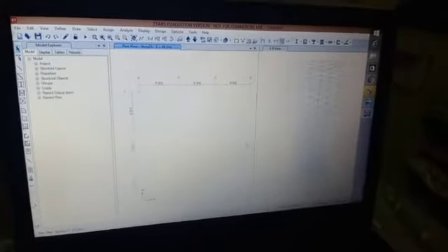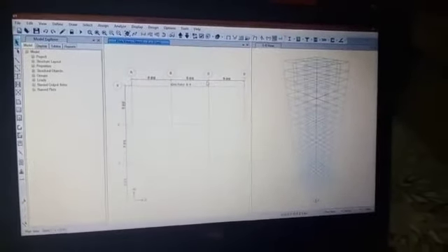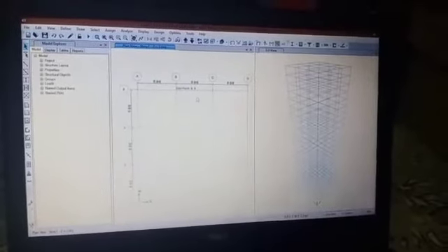Now you have added all the required beams and columns for the design of this structure. You have added beams of 500 by 300, 500 by 350 and 600 by 400 mm and columns of 500 by 500, 500 by 550 and 600 by 400 mm, and you have created auto list property for both the columns and beams which are used to create beams and columns in the similar stories, which are 1 to 8, 9 to 14, 15 to 20 and 21 to 23. Now we have finished defining all the required elements of the building.